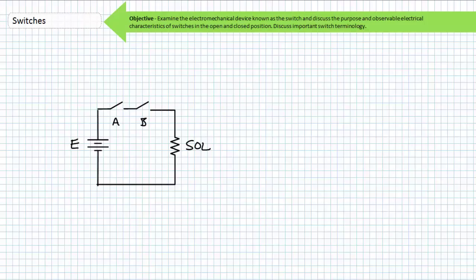The only way an operator can operate the hydraulic press is if they close both switch A and switch B simultaneously. If neither switch is closed, the press obviously won't operate because the solenoid obviously can't receive current via the two opens in its path.